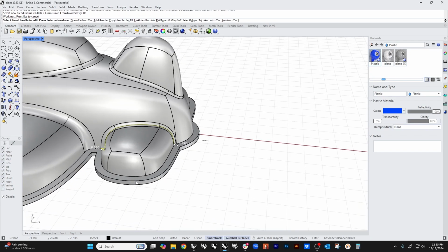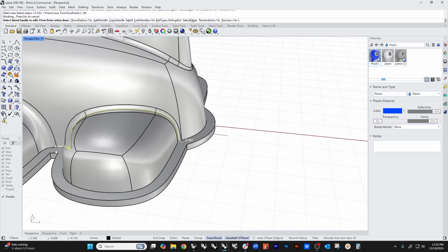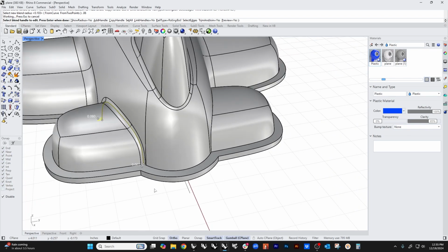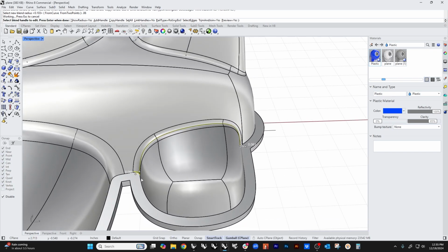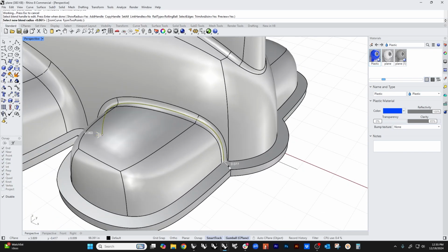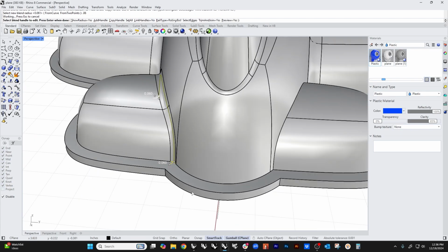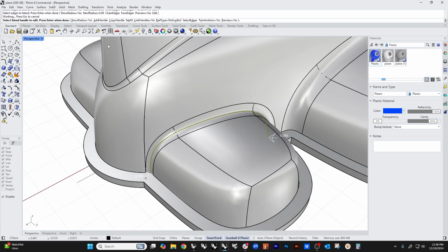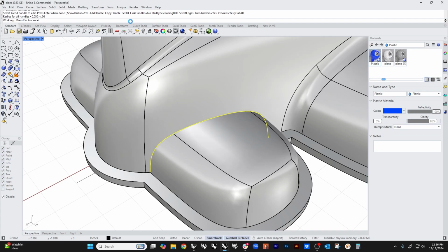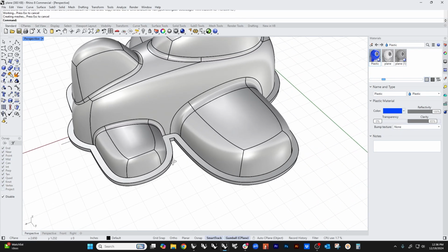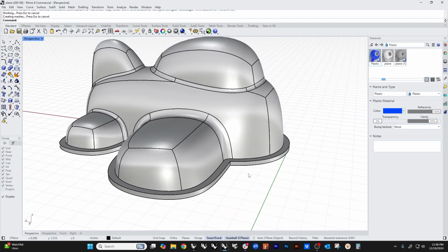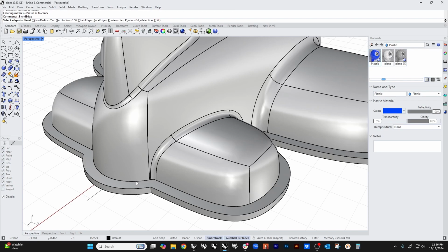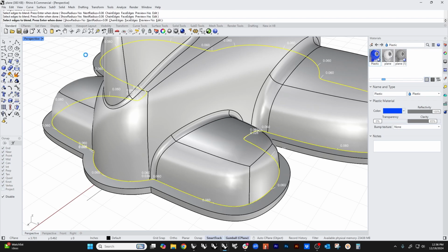So we need to remember that, because when we go to put a fillet around the base of this, we can't go any bigger than 0.06. In fact, we probably have to go a little bit smaller than 0.06. So let's do 0.06 here, and 0.06 here, just so they match, and that way it's easy to translate it to the other side. So we're going to set all 0.06. And so we've got most of our filleting done here. So we know that this is 0.06. This is the smallest value. So when we do this, we can't do 0.06 because it's going to fail.